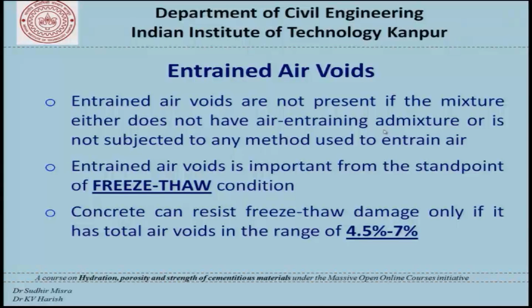In another case, if you do not use any methods by which you create air bubbles in the mixture, in that case also you do not have entrained air voids. The other way of understanding is that entrained air voids can be imparted in the mixture either by using an air entraining agent or by using other methods by which you can pump air bubbles into concrete.